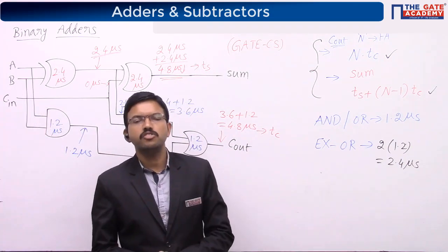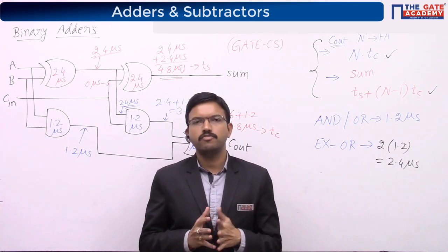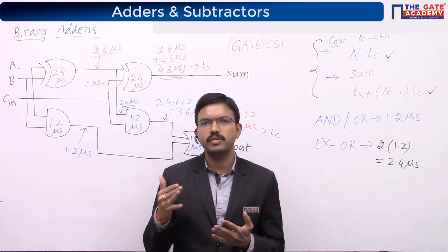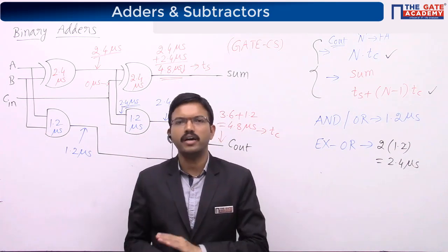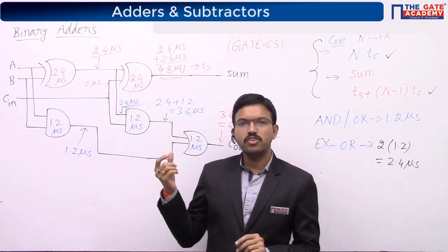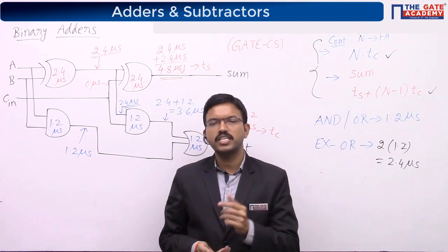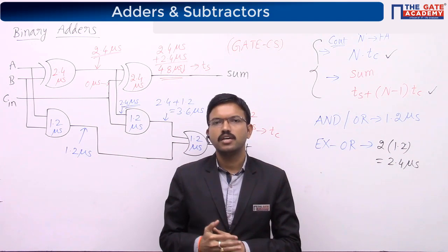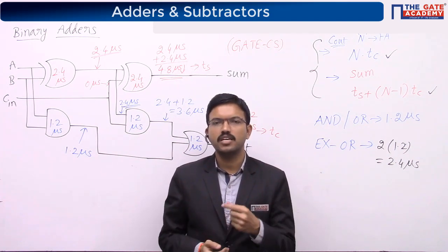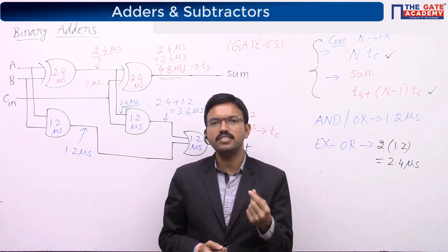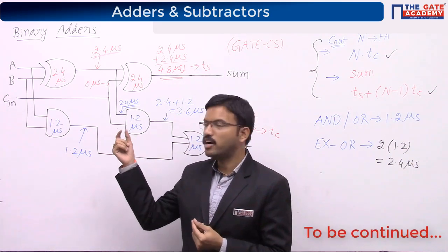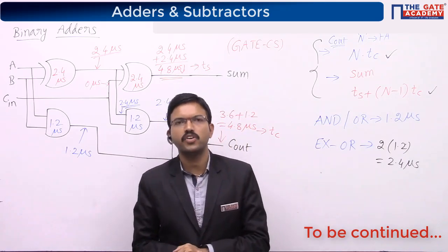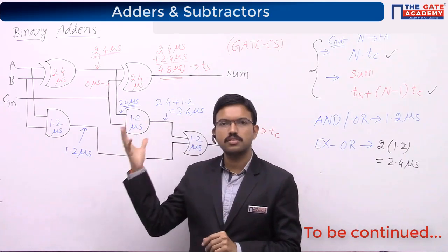Right. So, up to now, we have discussed binary adders. We started with the 1-bit binary adder, that is the half adder, then the full adder, and then the 4-bit binary adder, like that. Like that, we have implemented higher order binary adders. When you consider the half adder, there you have considered the carry. Similarly, you will have the half subtractor, full subtractor, and then the 4-bit binary subtractor. There you require difference and borrow. Here we have considered sum and carry; there you have to consider difference and borrow. Similarly, you can try those subtractors later.